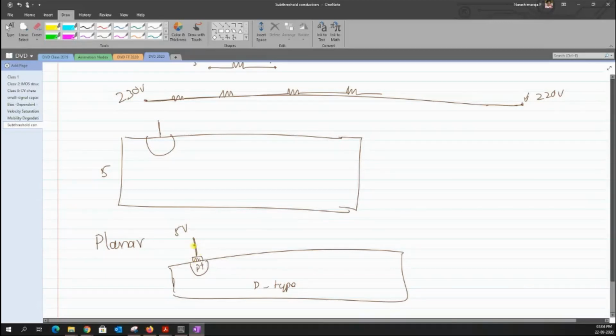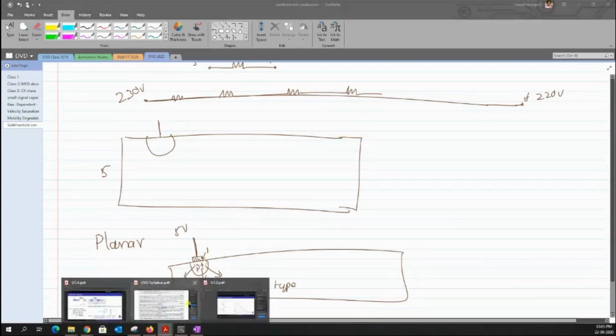So what happens is that the current flowing through this shorter wire will have a much larger resistance. And again, when I'm entering into the substrate, I need a low resistance path. So what we are really trying to do here is reduce the voltage that is getting dropped here. We want the voltage that I have here to be as uniform as possible across this entire surface. It is something like reducing the resistance, not much physics behind this particular P plus region. Okay. Done, sir. Sorry if I couldn't explain properly.